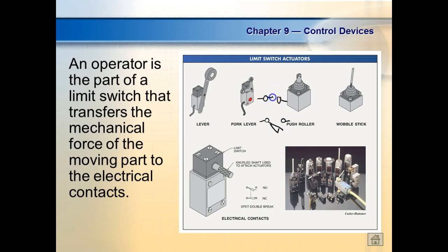Yeah, but it's going to be on the top. So normally closed goes across the top. Now, if it was drawn like this and it was up in the air, then it would be a normally closed held open. So these are symbols for our limit switches. Now what this would do, this would actually have a dashed line between them, if we could have it, on this guy right here, because we have a normally open and a normally closed inside this one thing, right?